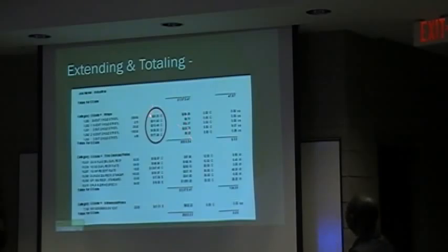So here it's telling us that $91.51 per 100 of this is installed, and when you divide this by 100 and multiply by $91.51, it's going to give you this value. And that is how we come about the cost of installing these categories of fixtures and materials shown there.